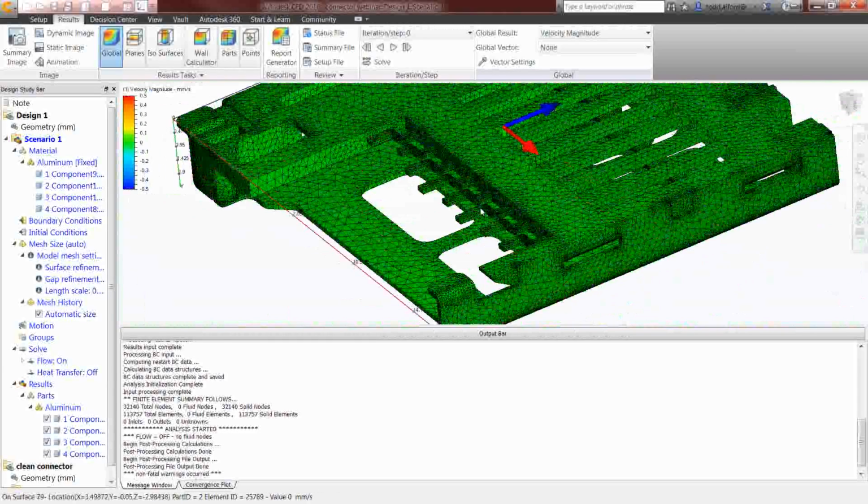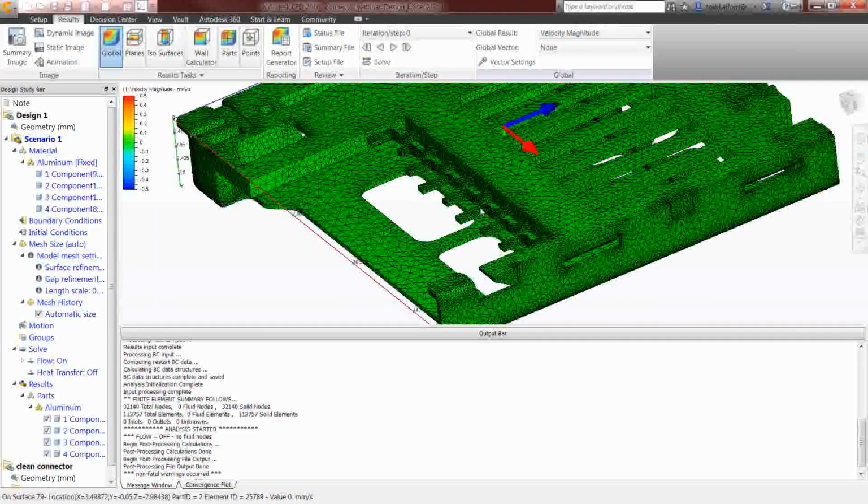It's not saying that if you have a small edge or a small sliver it won't mesh; it would just be concentrated, but that's more than likely the case. And it's not to say that small part and model gaps won't mesh just because they're small. The mesh is pretty robust and may surprise you. But what will always happen is that you will have more mesh in those areas than is probably necessary.